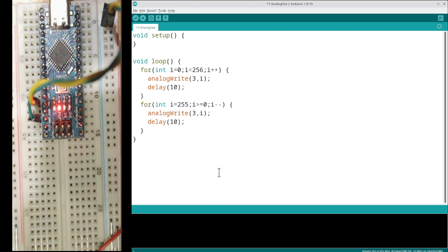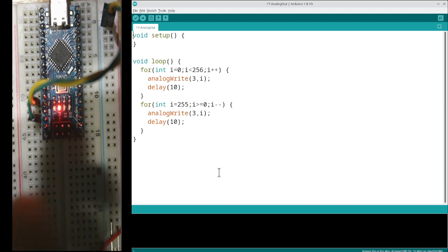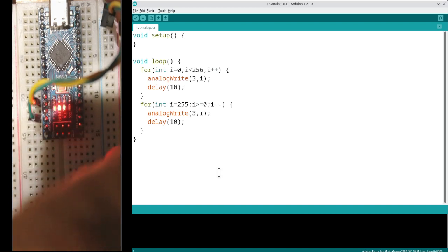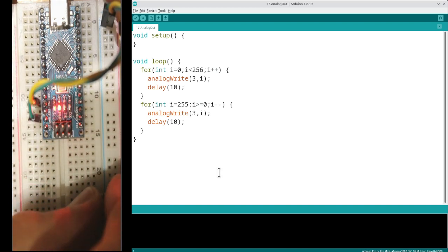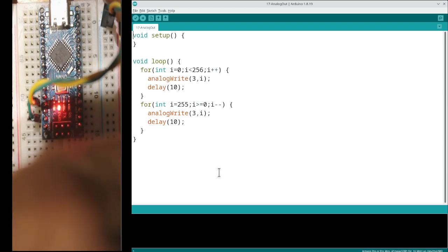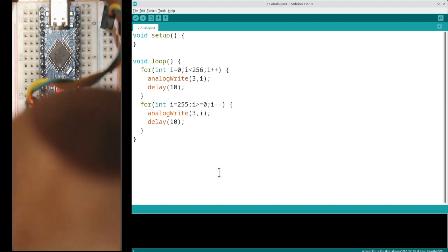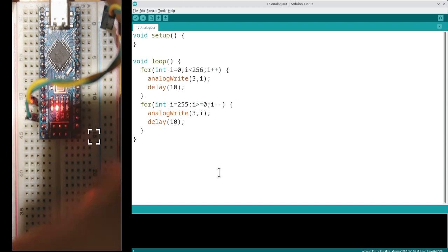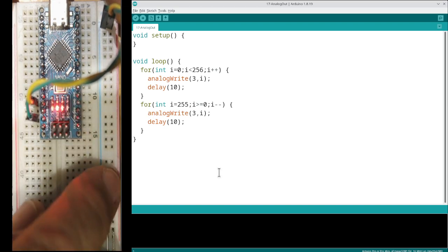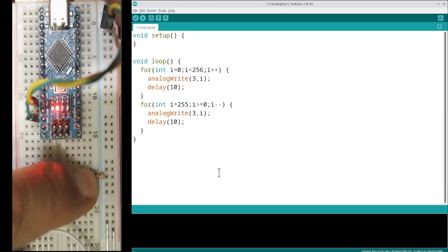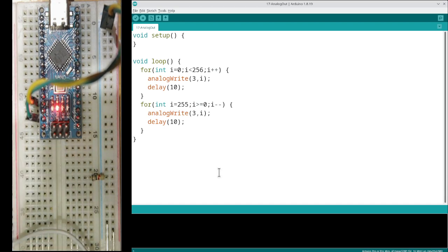And we're going to take our 1K resistor, because now we're working with an LED with an output, and so we don't want to blow our LED. Okay, so there's our dropping resistor, or our current limiting resistor. And I'm going to now put an LED in there.